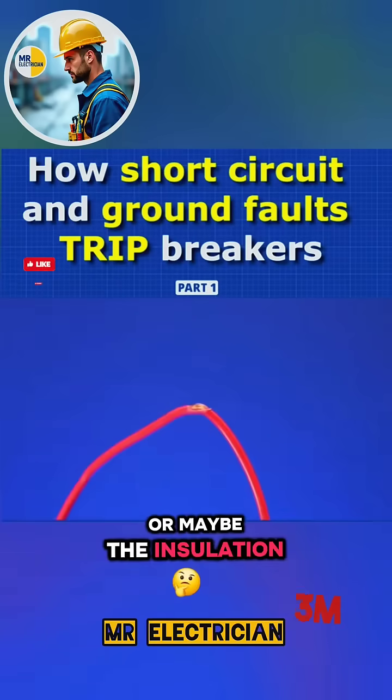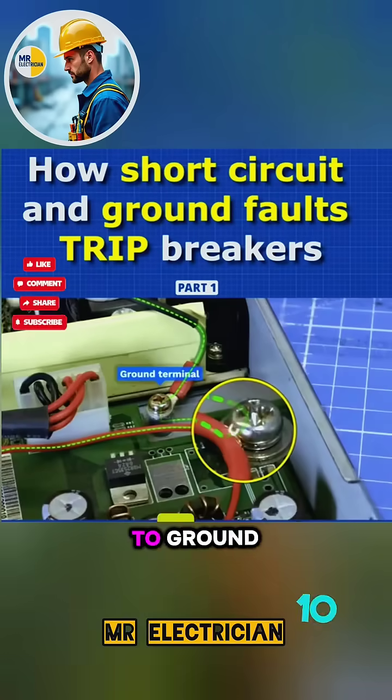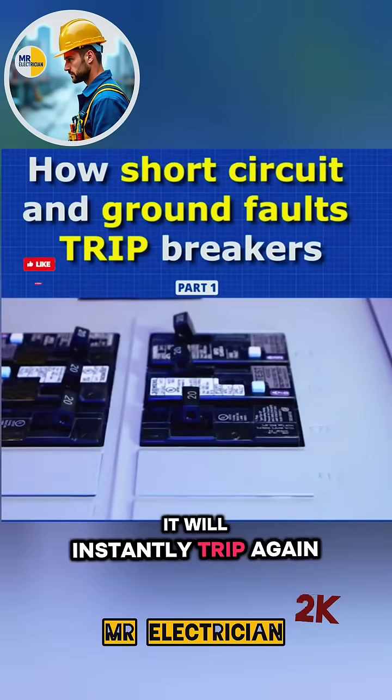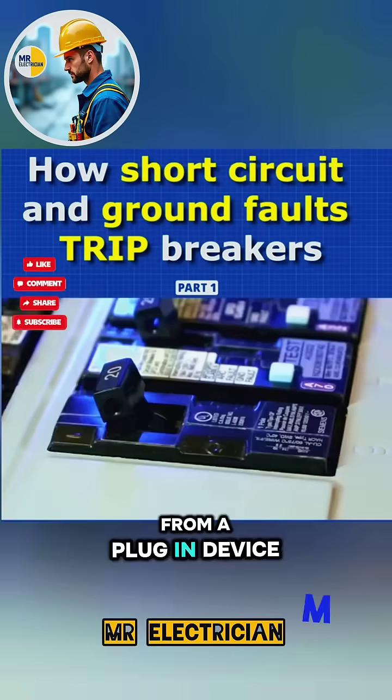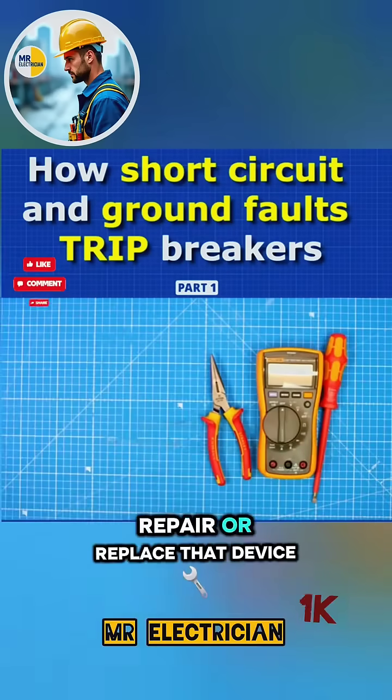Or maybe the insulation of the wire in a device has been damaged and the current flows through the metal case to ground. Regardless of the cause, if we try to reset the breaker, it will instantly trip again. If the fault occurs from a plug-in device, we can just unplug this and the breaker should reset. We then need to repair or replace that device.